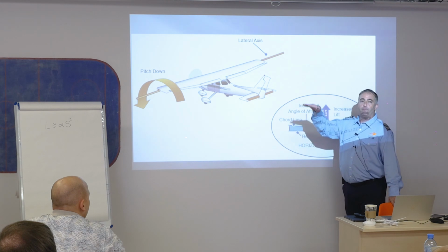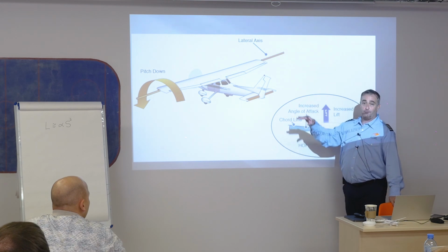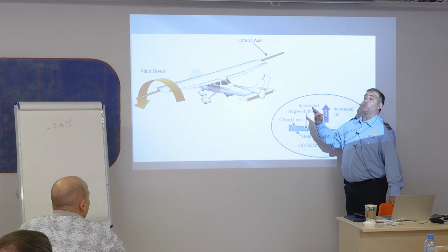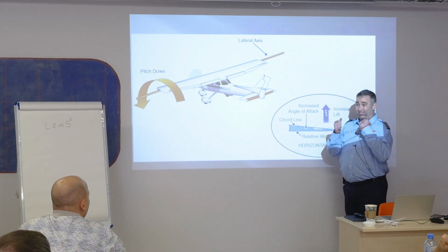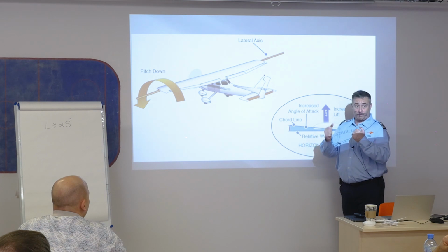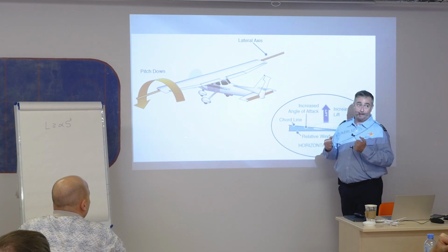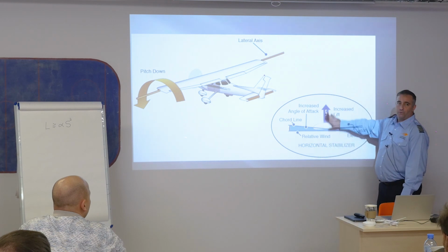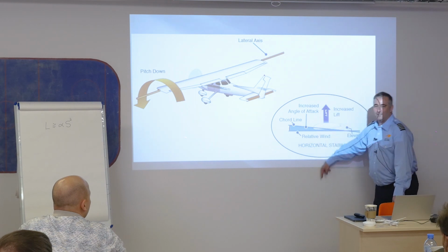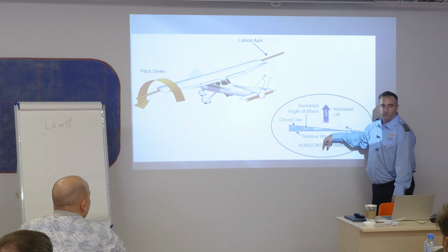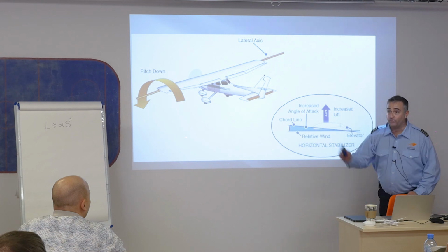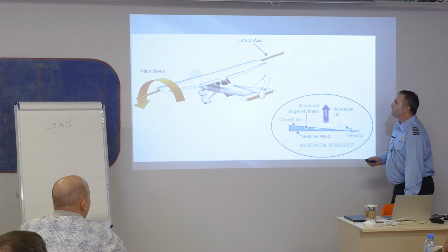It would not exhibit positive static and positive dynamic stability at all. It would be borderline uncontrollable, and it would consume all of my resources and mental capacity trying to keep it in the air. Okay? So this lift that we're showing here is actually just less of the actual tail down force. All right? Remember, one of our key terms was down force, that tail forcing down.